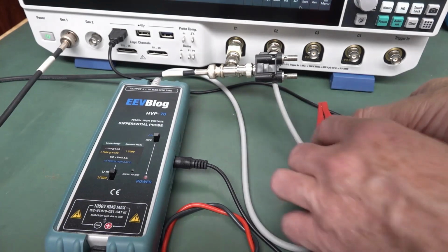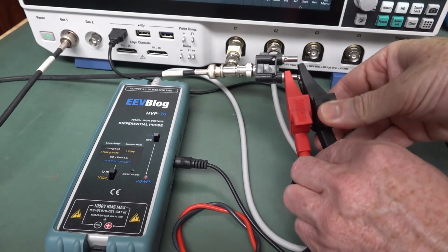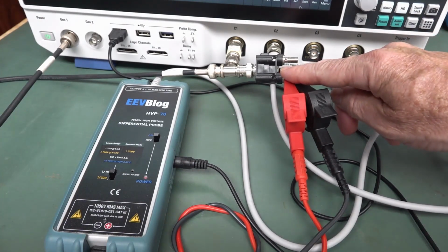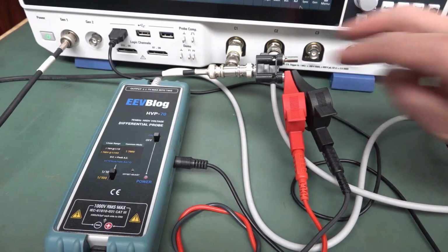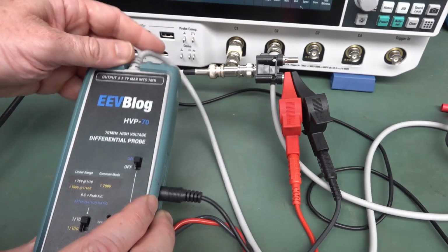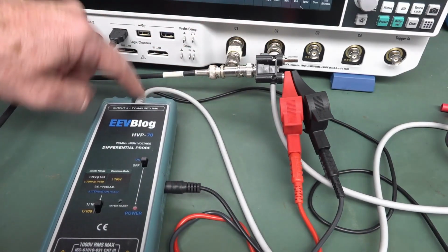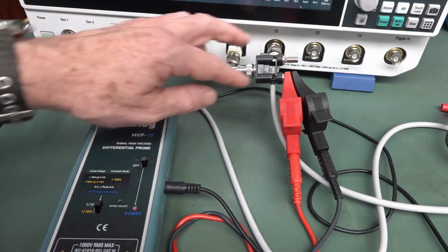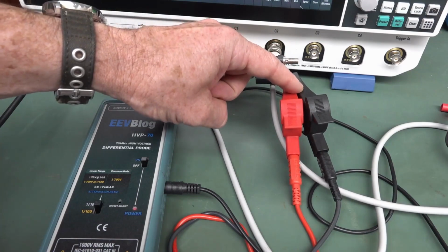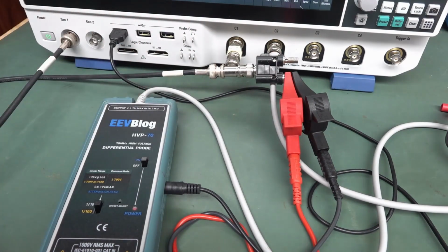So what we want to do is connect both of these inputs together, short them together and connect to the positive input like this. Why the positive input? Because it means that we're applying a voltage relative to the output here, because the output is ground referenced like this. So we're actually referencing it to the output. So we're effectively feeding that signal generator voltage into both of these leads, i.e. a common mode signal relative to the grounded output.